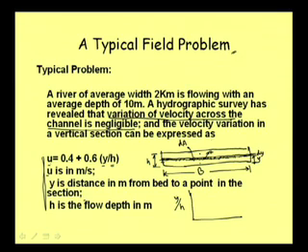So, at every point we put y/h, and on this side we put the u velocity which is actually observed, and then we get a relationship between u and y. For that curve, you can see when y is equal to 0, that is when we are at the bed, your velocity is in fact not equal to 0, it is equal to 0.4 when y is equal to 0.